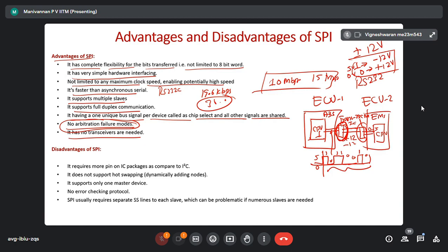Please know that it will be inside your computer. Don't worry, everything is inside. In the motherboard, wherever the port is there, RS-232 is there. But you need this, which is called the transceiver level shifter. Other name is called level shifter. What does it shift? The voltage level: 0 volts is converted to plus 12 volts, plus 5 volts is converted to minus 12. Correct? But inside the CPU, you need 0 volts or 5 volts only.